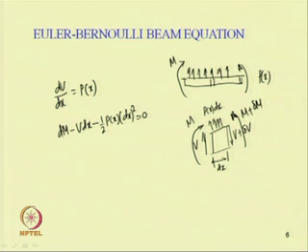For the limiting case, dM/dx will be equal to V. This means the rate of change of bending moment along the beam is equal to the shear force.